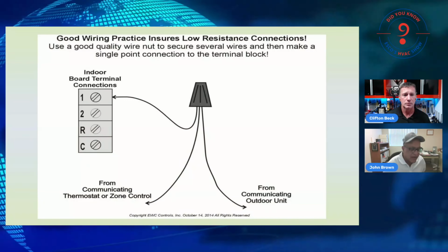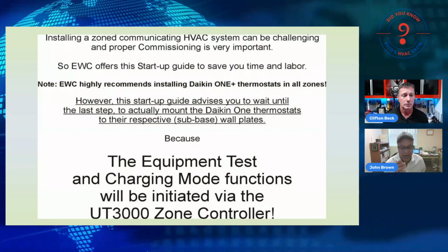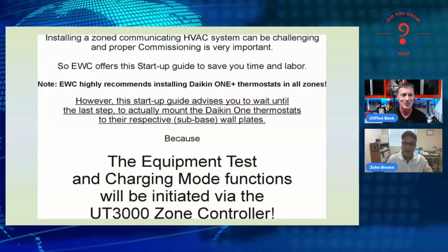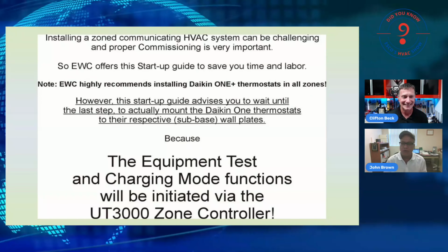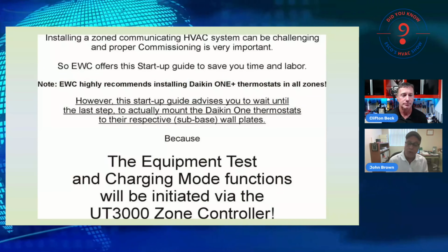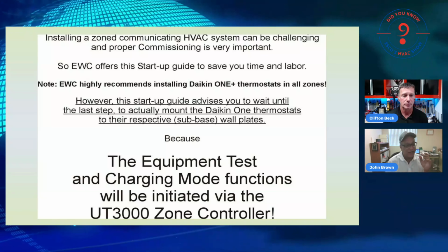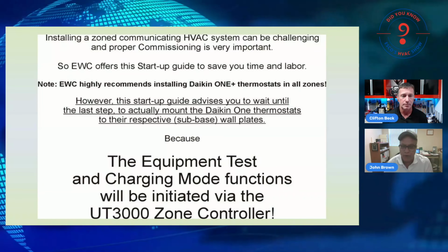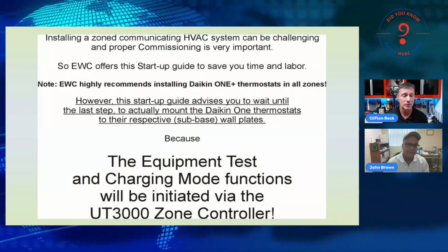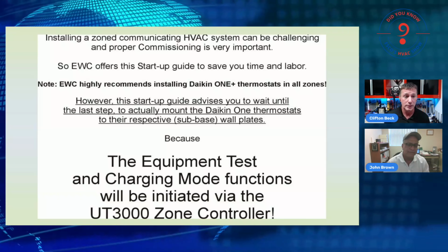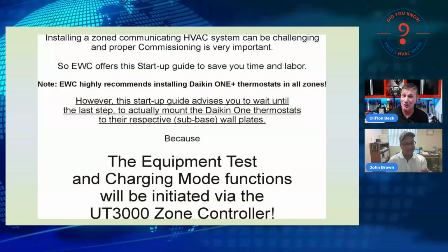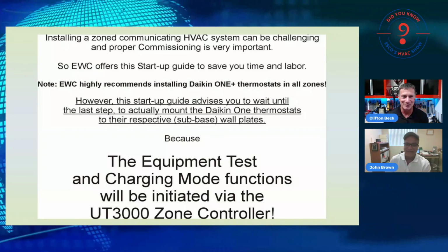You're exactly right, Clifton. I ran into this on a job. Believe it or not, I got a call from Hawaii. Well, this guy's splice connection from the indoor to the outdoor was so corroded, it simply would not communicate with the outdoor unit. It took him a while to find it, but he did, cleaned it up, and it worked like a charm. Thanks for pointing that out. Yeah, I always told guys, if they have an issue with the outdoor unit not pulling up onto the network and they're reusing wire, find the closest window or door, grab you a spool of fresh conductor wire, throw it outside, and run you a fresh new line. We've actually done that. Absolutely have done that. That's a quick way to find out.